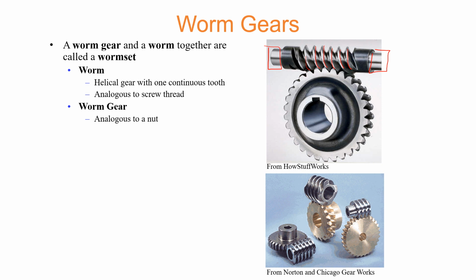This is going to have two bearing surfaces, and the axis of rotation is going to be this, about which the rotation may happen. So when the worm is going to have a rotation, the worm gear, which is also going to have an engagement at this particular place, is going to have a rotation as well.